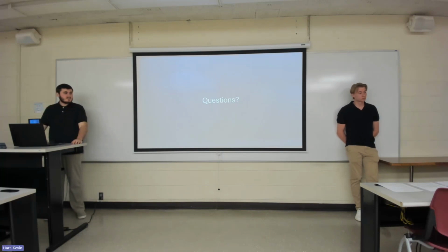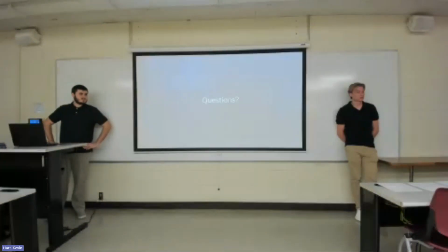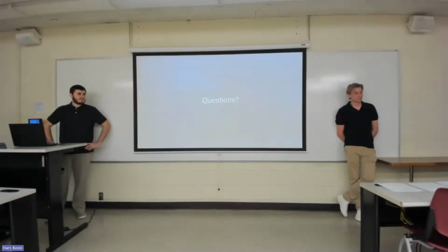The load case of the curb strike. Yeah, curb strike sideways is probably a real common kind of thing. And what I've seen is if cars are sliding on the track and they slip into a rut, these are not nice flat roads. They have all kinds of whatever. And so that sideways hit on the bottom is real. That's an important load case. A lot of cars break, so concentrate on that one.